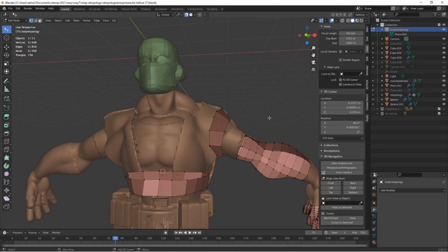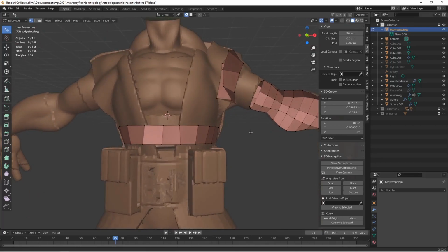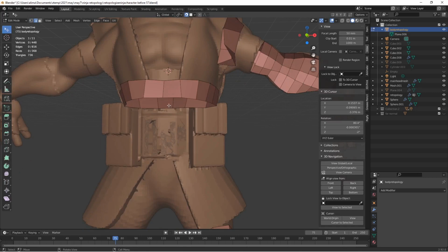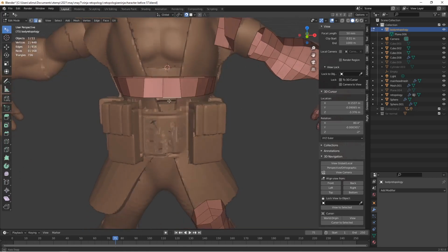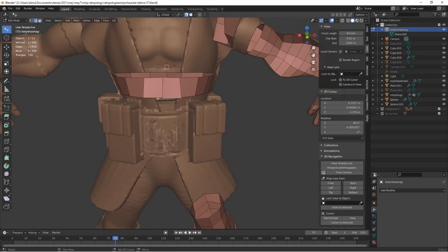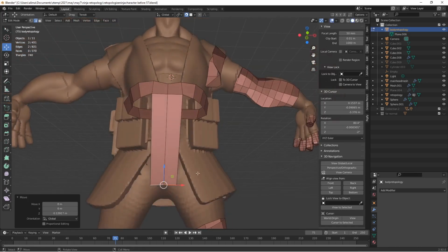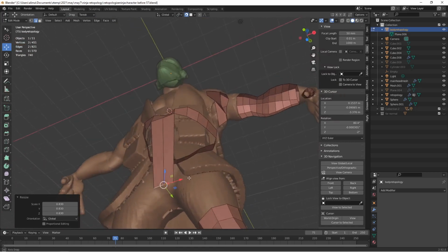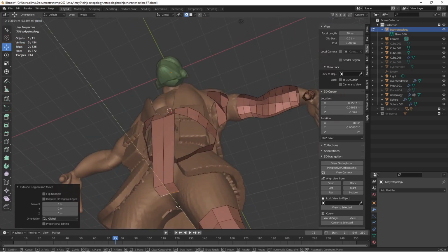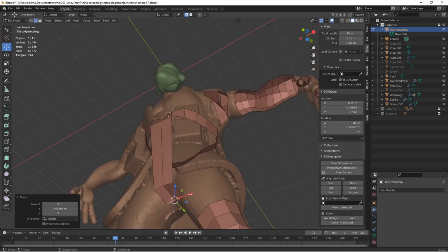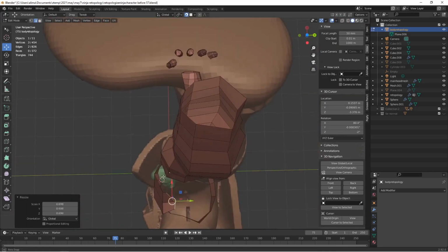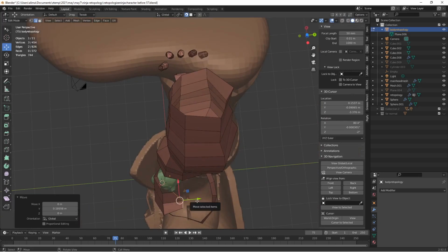Okay, what we're going to do now is hold shift as well as the middle mouse button to pan. I'm going to go to the upper left, go to edge select, select this edge here. Now we can select both edges. We'll press E to extrude, bring this down like this. So I'm going back to the move tool here, bring that down like that. So now I'm going to press E to extrude. Press S to scale that. E to extrude.